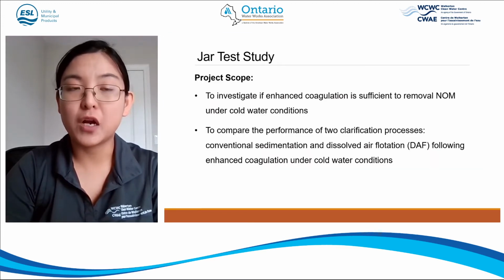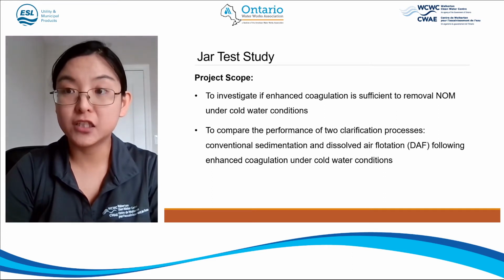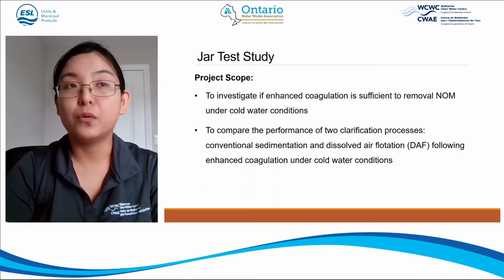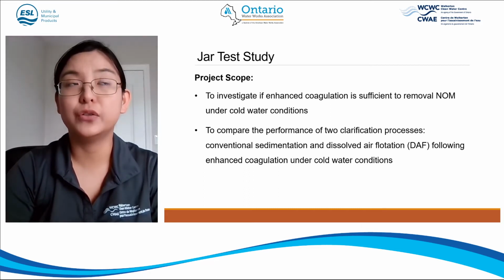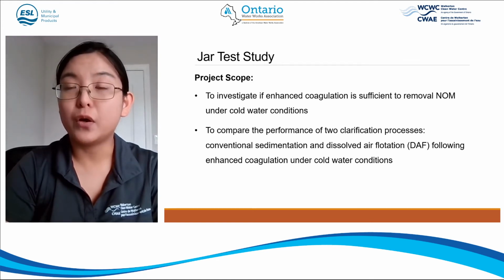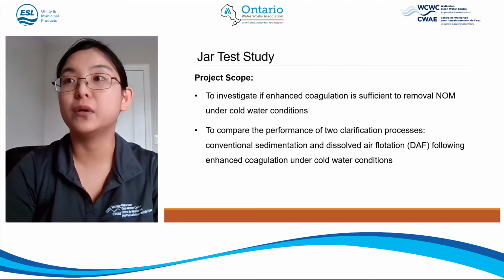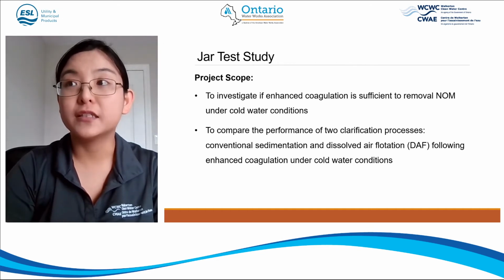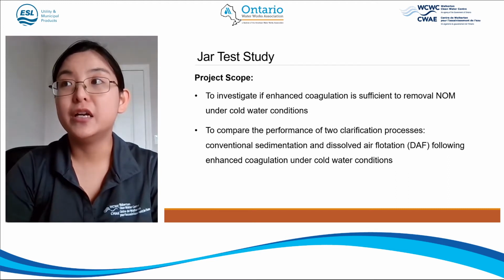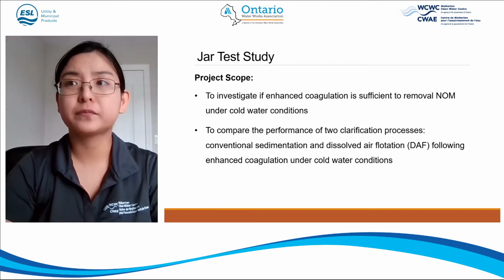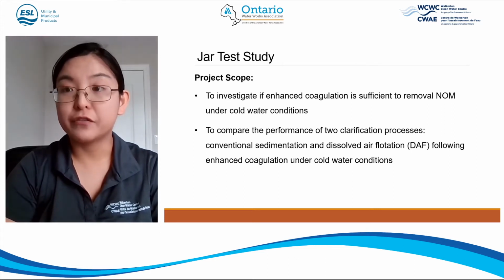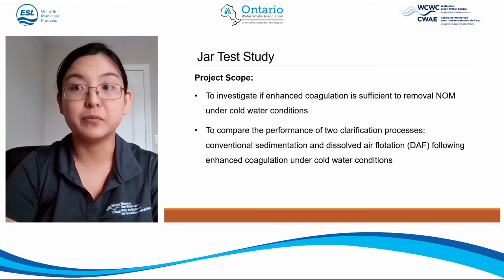So during this project, this is the bench-scale jar test study. Right now the community has been on a boil water advisory since 2013. And the plan right now to get rid of the boil water advisory is that the community wants to retrofit the system with enhanced coagulation followed by either conventional clarification or dissolved air flotation. So they want us to test which clarification process works better for their community.